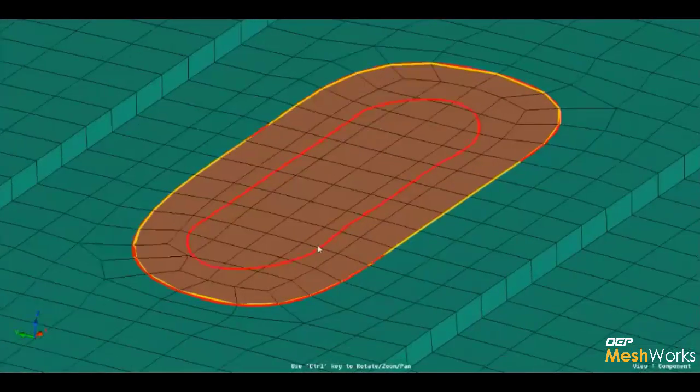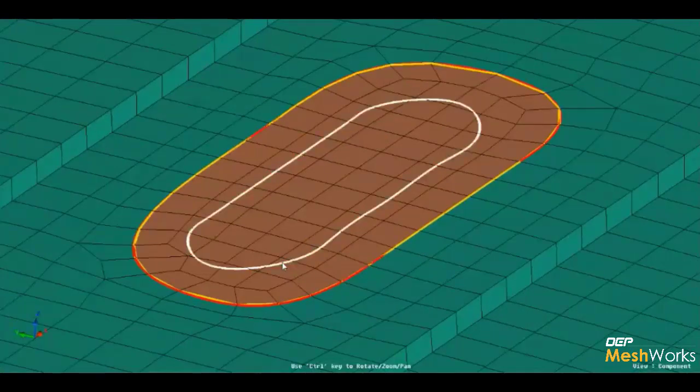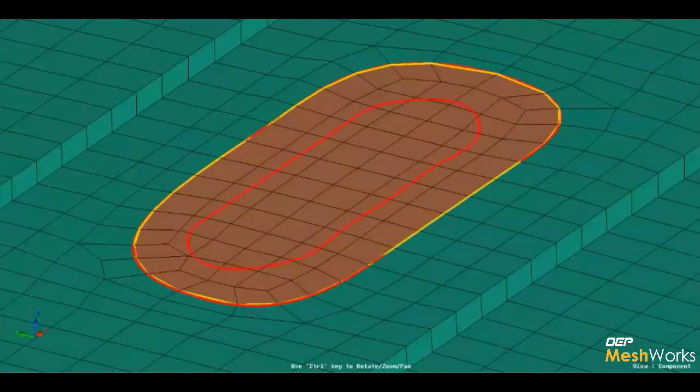So the next step is where the user will select, let's assume, this inner 1D element. So we will select that 1D and the user will specify the output as cells, but now the user can specify it with process sets, which is nothing but the output of an older process, whatever process we executed before. It will give some outputs to you. So that output you can select for the next input without selecting in the particular panel. So in the process sets, I will just select that.